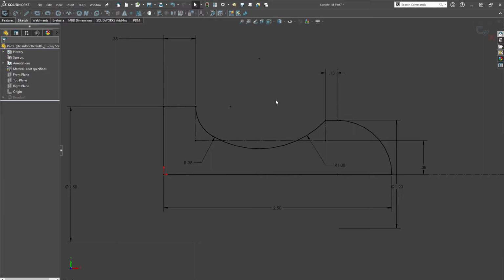There can be dimensioning drawbacks to that. If you start trying to model everything in one sketch, while it is efficient, it can be kind of a pain to come back later and change things. So sometimes I like to do exterior features and then interior features as two different sketches. And obviously one would be a cut revolve as opposed to a regular revolve where it adds material.